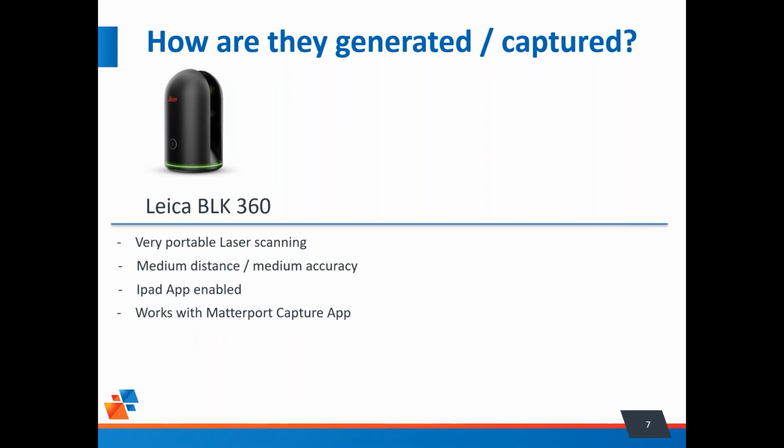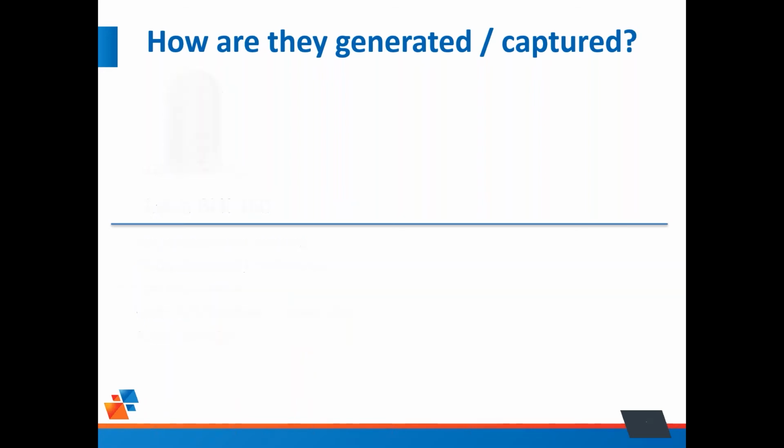You could do an interior scan extremely quickly with the Matterport and then add the exterior scans to get that point cloud data with the Leica in the same capture app. It also has auto registration as well. So it's a really good middle of the road kind of solution.